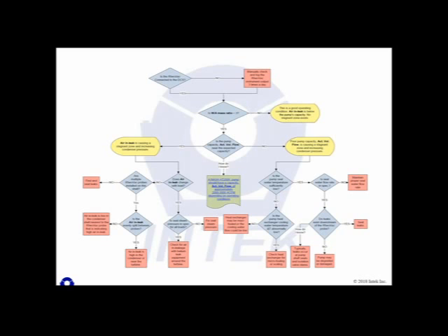And so this flow chart summarizes what we've just talked about. For the next couple case studies, take a look at this flow chart. I just want you to focus on 2 diamonds. You can look at this in more detail later on after the class. This is a whole troubleshooting effort for looking at air in-leakage or vacuum pump problems. But I want you to use these 2 diamonds on the next couple case studies to figure out what the problem is. Number 1, is the water to air mass ratio less than 3? If yes, then you've got a problem. If no, you've got no air in-leakage related problem, okay?